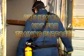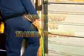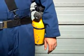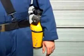Usage is normally limited to when there are extended work periods required in atmospheres not immediately dangerous to life and health. A combination respirator has an air supply component, plus an auxiliary self-contained air supply to be used if the primary supply fails. The self-contained portion can be small, since it only needs to supply enough air for escape, and usually has enough breathing air for a few minutes in a self-contained tank.